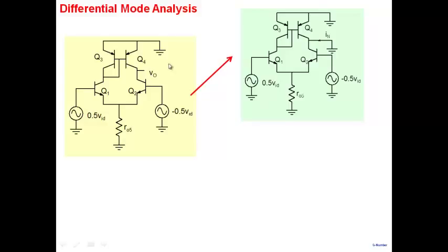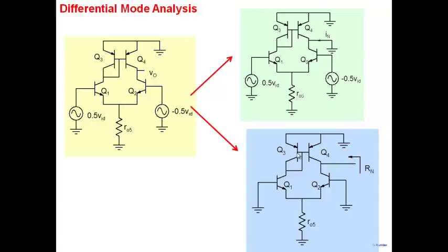And so the first thing that we try to do is determine the Norton's current here. What we do is we take this particular node and ground it, and whatever is the current flowing in, that's the Norton's current. So we try to determine the Norton's current first. And the other thing that we'll do is determine the Norton's resistance here.